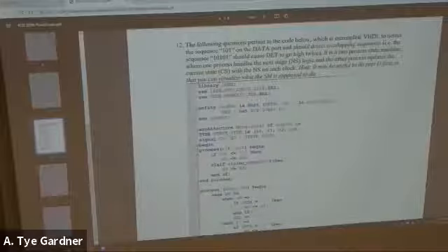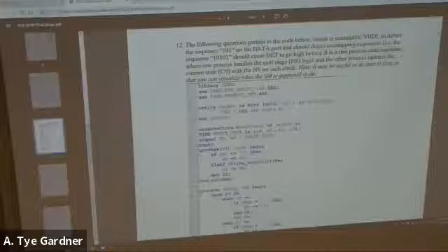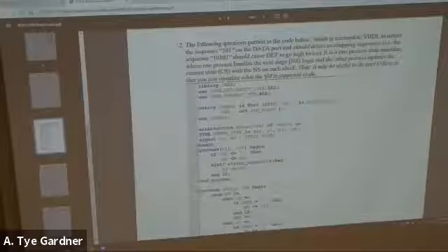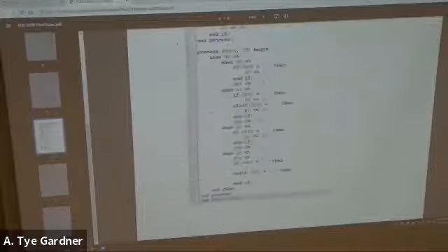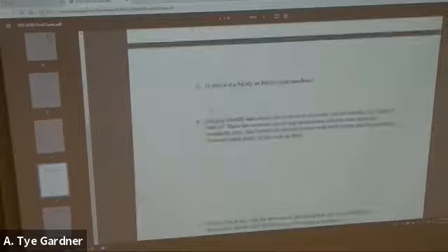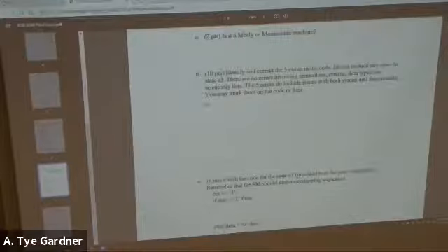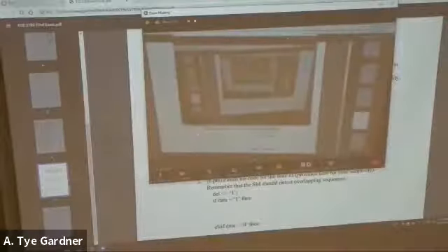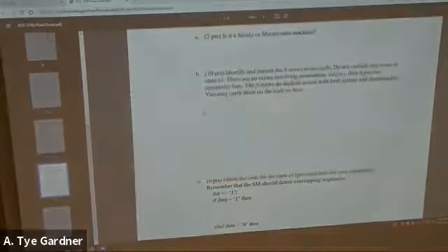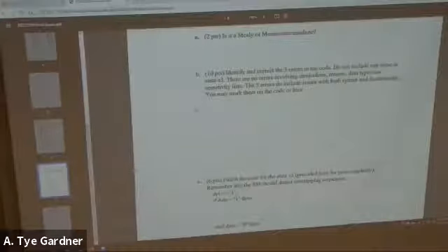It's a 2-process state machine where one process handles the next state's logic, and the other process updates the current state with the NS on each clock. So I'll come back to the code in just a minute after I show you the questions. People in video can flash back and forth if you end up rewatching this.